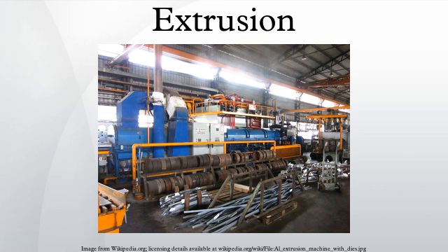The complexity of an extruded profile can be roughly quantified by calculating the shape factor, which is the amount of surface area generated per unit mass of extrusion. This affects the cost of tooling as well as the rate of production. Thicker sections generally need an increased section size. In order for the material to flow properly, legs should not be more than 10 times longer than their thickness. If the cross-section is asymmetrical, adjacent sections should be as close to the same size as possible.